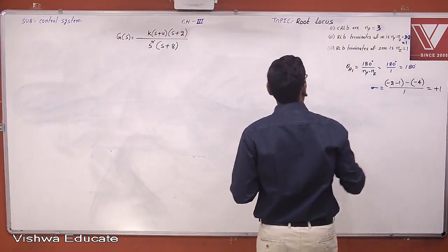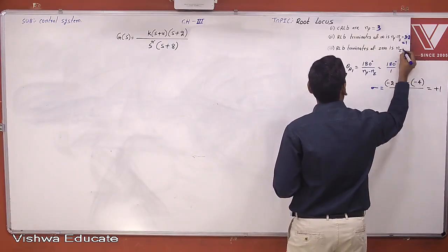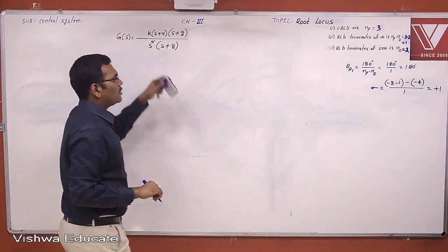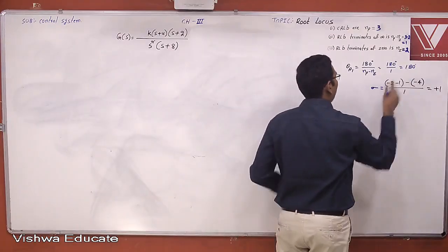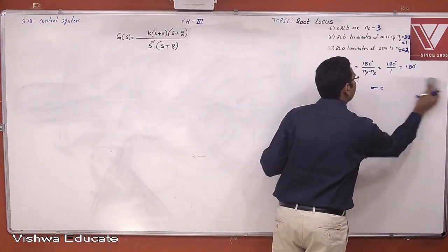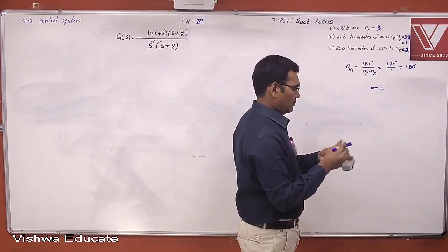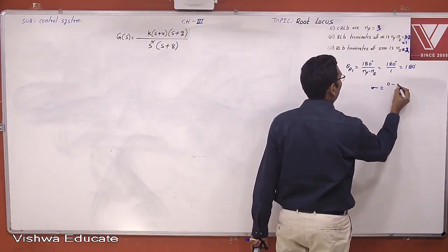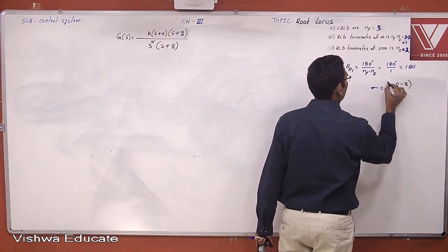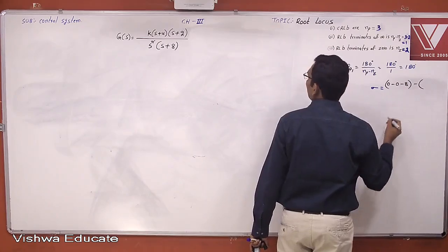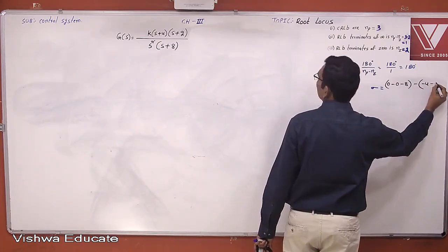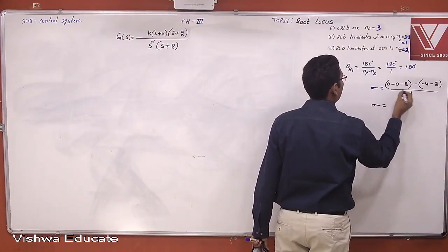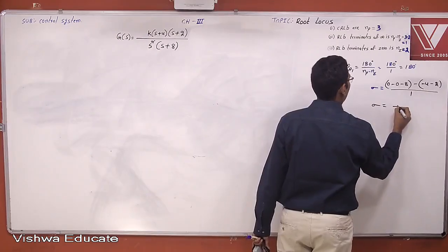The number of root locus branches terminating at zeros is nz, which is equal to 2. So how many angles of asymptote? 3 minus 2, 1. Therefore only one angle of asymptote. The centroid sigma is the sum of the real parts of poles minus the sum of the real parts of zeros, divided by np minus nz. Therefore the centroid sigma is minus 8 plus 6 minus 2.